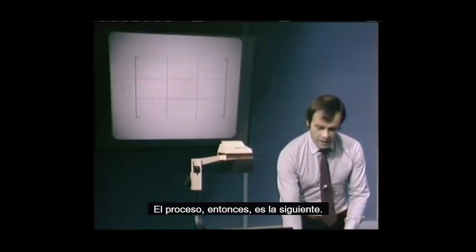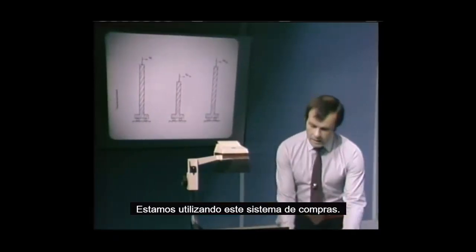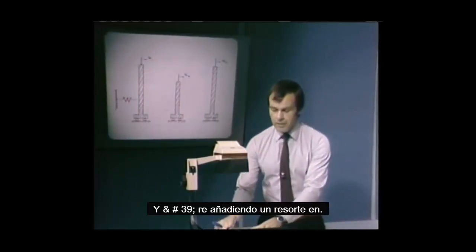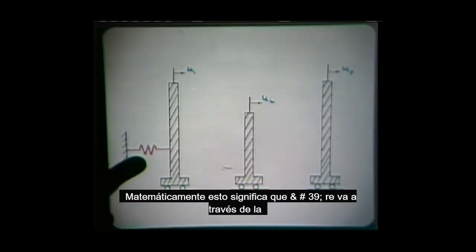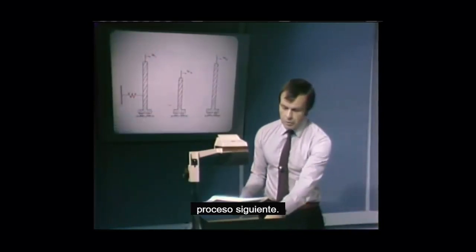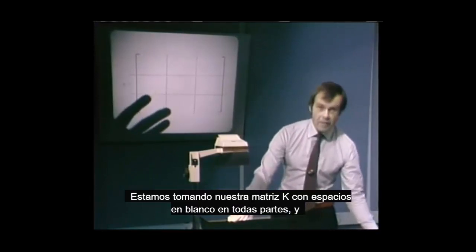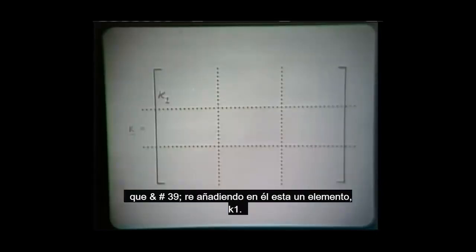The process is the following. We are using this cart system and we're adding one spring on. That is the first addition, spring K1. Mathematically, we are taking our K matrix with blanks everywhere and adding into it this one element, K1.